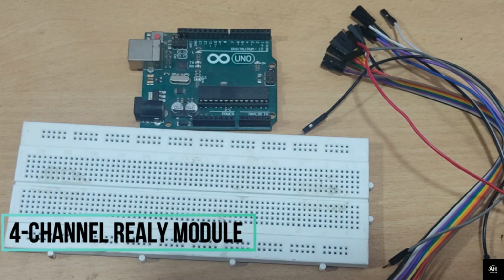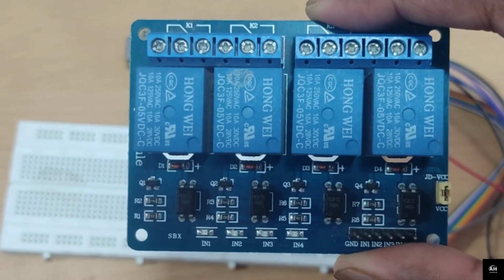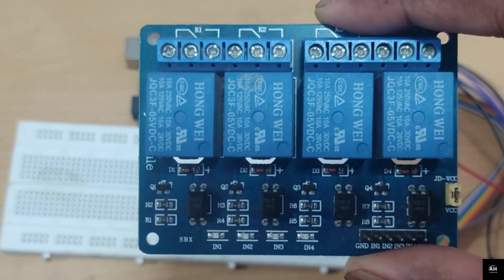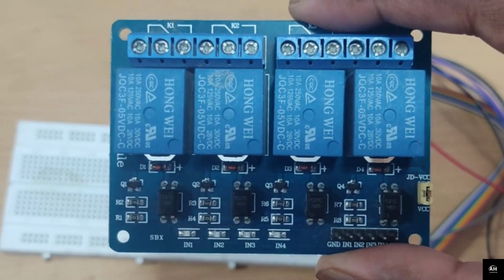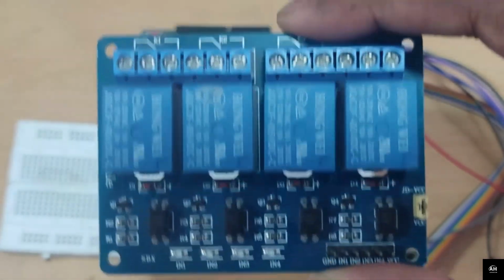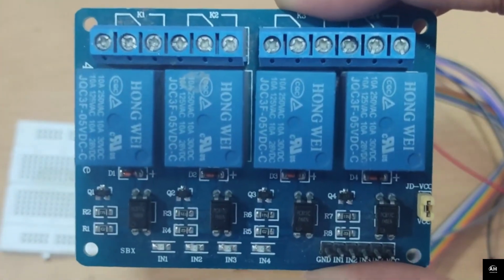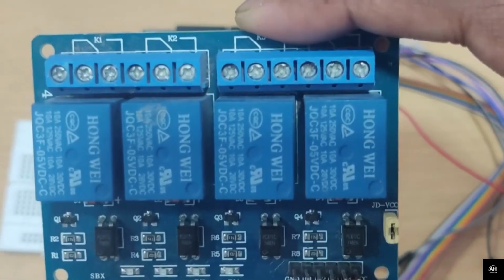And one of the most important components will be our relay module, using which we are going to be controlling all the hardware components that will be connected to our relay module. So using it, we are going to be controlling all the hardware components like light, fan and other devices with the help of this relay module and the Arduino board. So this is a 5V relay. You can find it easily on Amazon, and you can see it is a 4-channel relay, so you can connect up to 4 devices. There are different configurations of this relay module. It comes up to 32 relays on a single board, and you can get a 32 relay module and control up to 32 devices using the Arduino board. So let me put it aside.